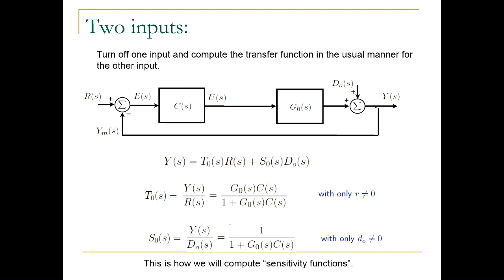Why is this significant? Well, first, large input signals might saturate your actuators. They also may mean that you are applying a lot of energy to control your system, a lot of effort. Large control signals mean a lot of effort. So that's why we might be interested sometimes in U being the output of the system.